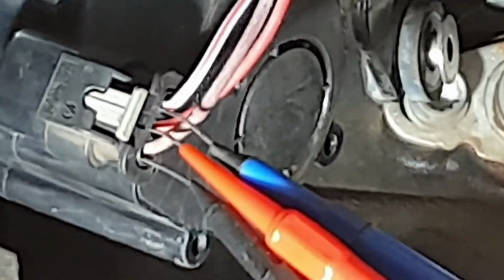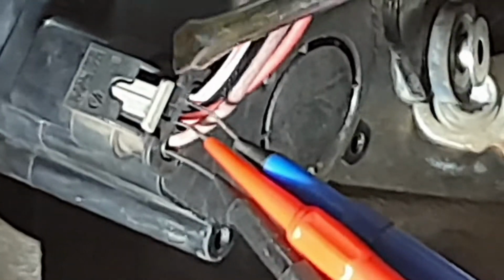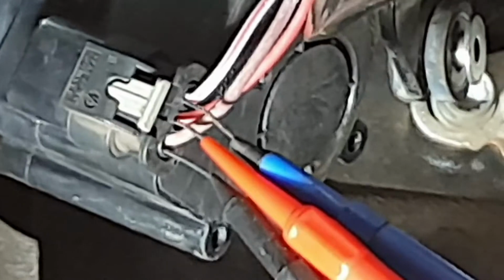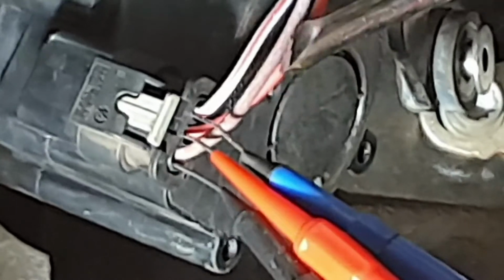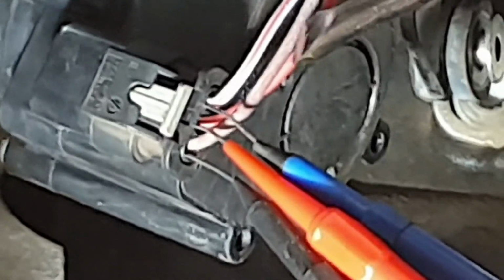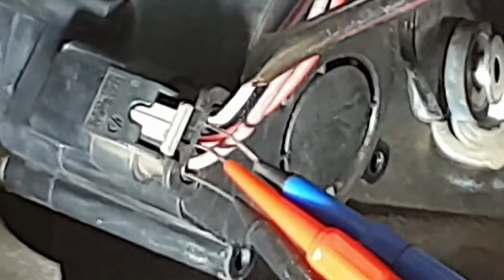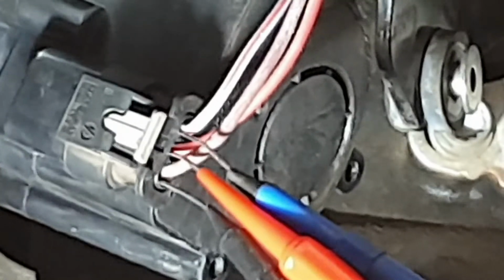So once again, this is the signal wire or the control wire connected to the ECU and to the pump, at the connector at pin 3. The middle one is pin 2, the red one, the power supply, and the brown colored wire is the ground side of the circuit.